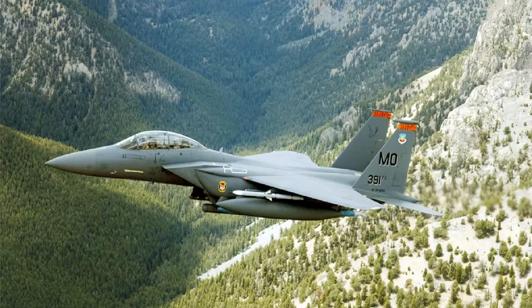Obviously, the geometry of the diffuser has to be specific to the speed the aircraft is flying. Therefore, if the aircraft is to fly at a range of speeds, some more complex system will be required. Generally, the convergent-divergent diffuser is only suitable for short bursts of supersonic flight, at less than Mach 2, such as on the F-15 fighter shown here.